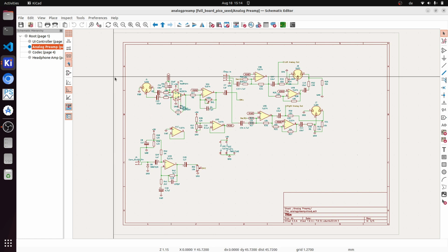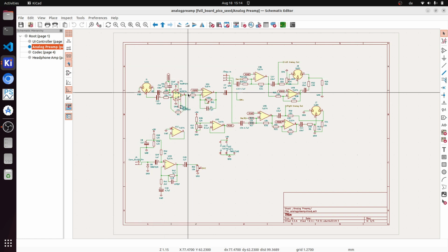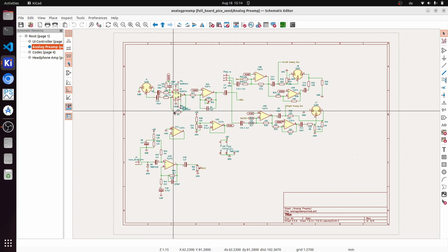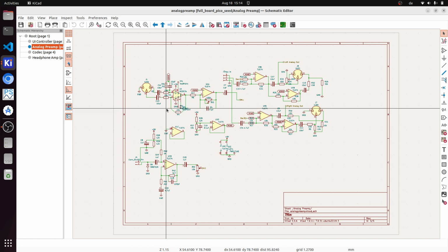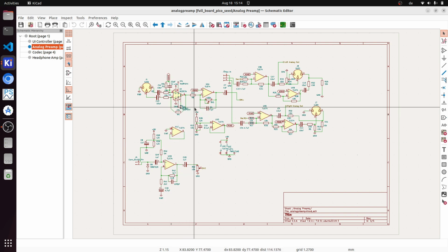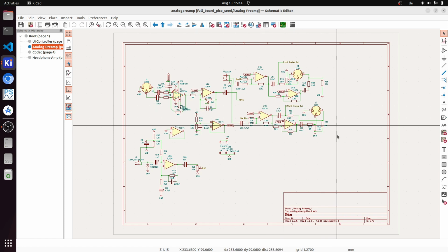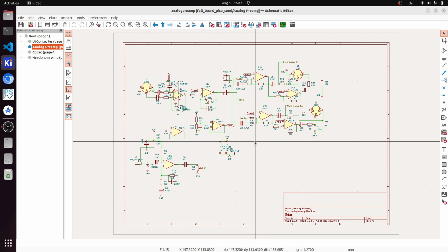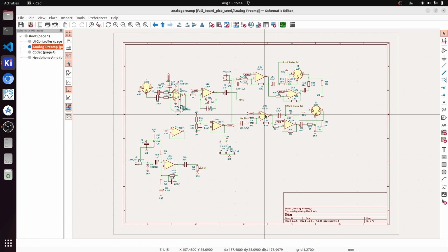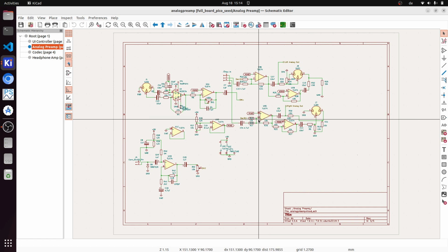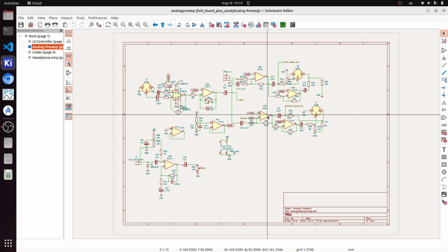The analog preamp shows different sections. Here we have the microphone preamplifier part, which is built around the NE5534 op amp, a pretty common design in many pieces of audio equipment. There is nothing special about this. And then we have the output stages here. This is a stereo out, so we have 2 times the same circuit, and the symmetrization is done electronically and not using a transformer, because I'm quite confident with working with op-amp circuits.